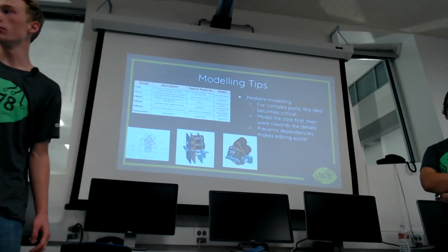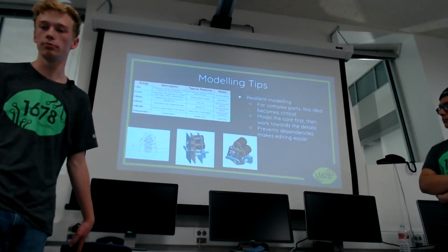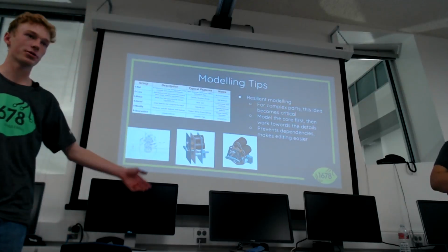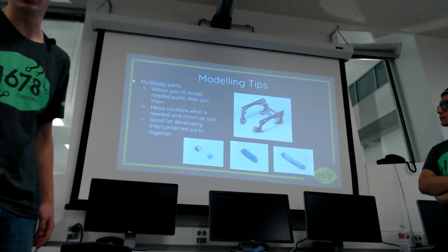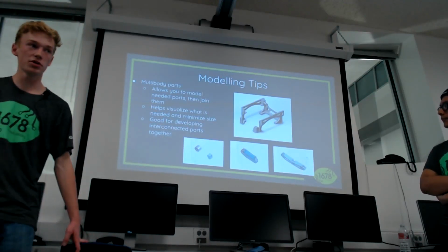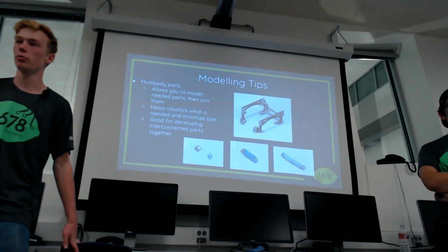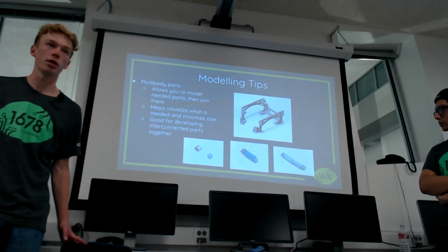And you're not going to have sketches referencing small details like fillets that might break your model later. This is, of course, not about 3D printing. This is a gearbox right here, but the same concept can be applied, and you can see that in this next slide. I don't know if you guys are familiar with multi-body part modeling in SolidWorks or whatever platform you use, but I have found it to be super helpful when it comes to modeling 3D printed parts.